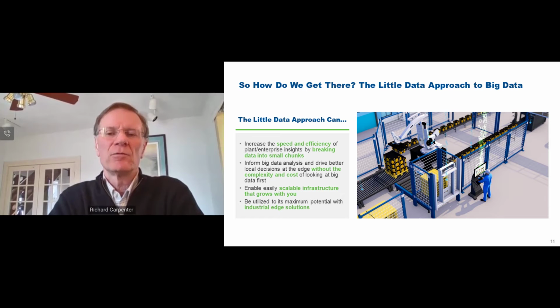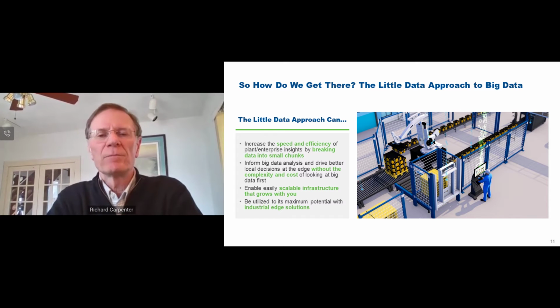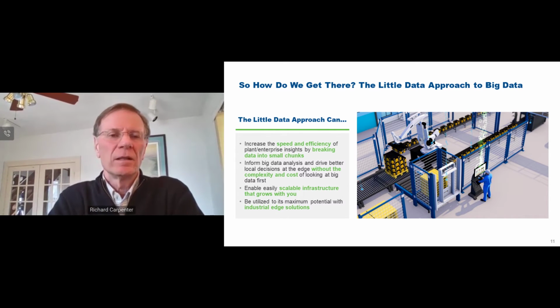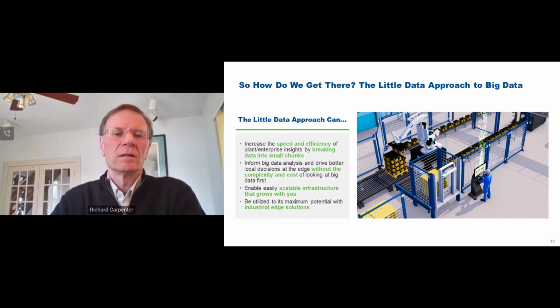Maybe you're sampling data for the cloud. Maybe for this type of application, you need to look at second that's more than 1 hertz in terms of availability. Second, you can't live in a partially connected world for some analytics. You want to be close to the edge so that independent of whether there's connection outside of the facility, you're still collecting the data and you're still running the analytics to help the operators. You can always use store and forward techniques on an edge processor to get the data offline whenever it's reconnected.